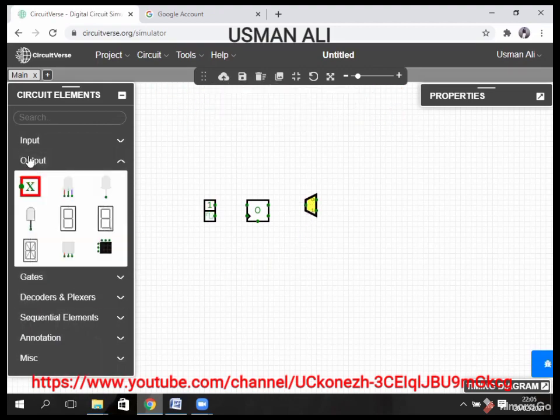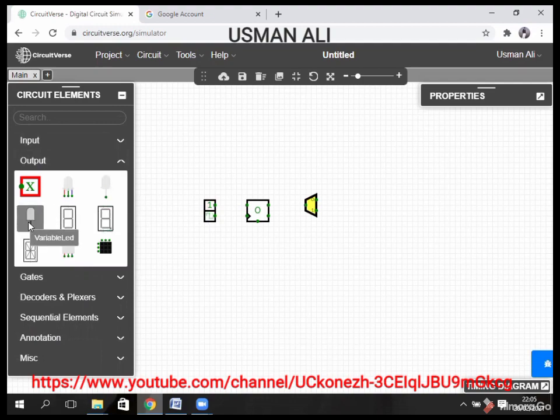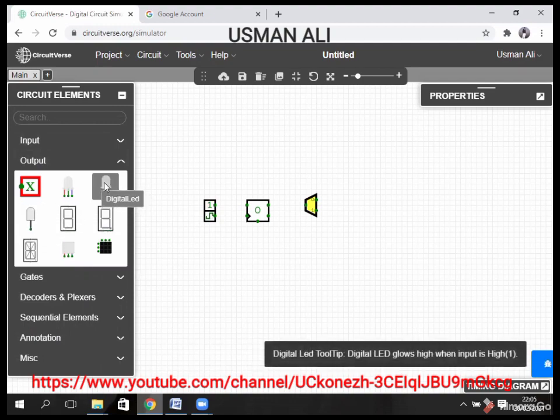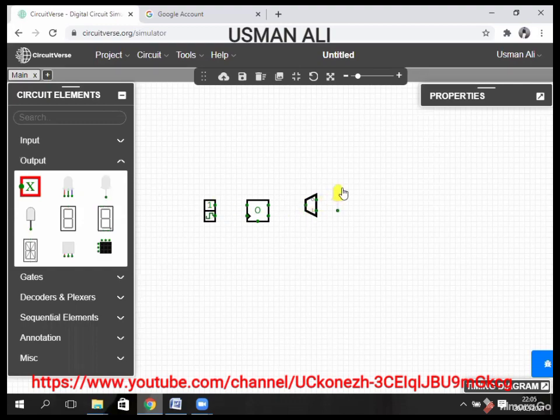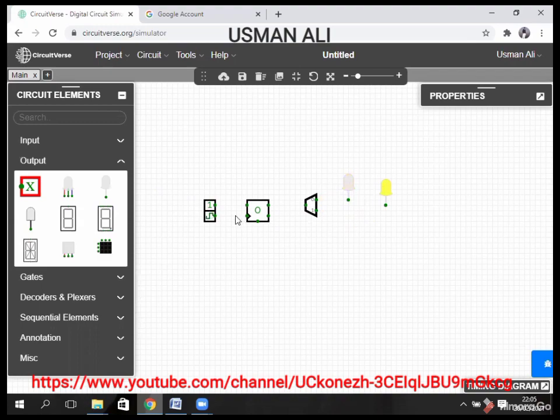In the output elements, you see there is a digital LED and a variable LED. You have to take a digital LED in our circuit, point it here, and take another digital LED and point it here. Now connect the first point to the first LED and the second point to the second LED. Put it down a little bit. Now connect our output value to our decoder, then connect our clock.